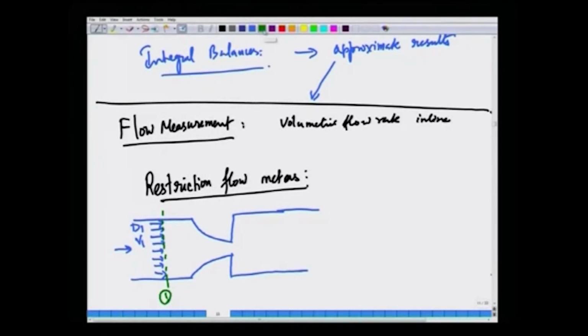Okay. The way fluid is going to flow is the following. It is going to flow like this. I am drawing it so that it expands slowly, and there will be recirculating zones. Now, we can put the control surface, station 2, somewhere here, where the fluid velocity is uniform in this direction, and it is flowing through. Let me also draw the streamline that separates in red.